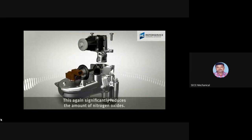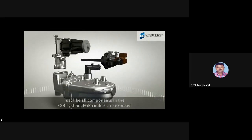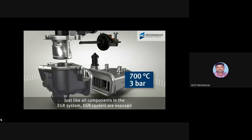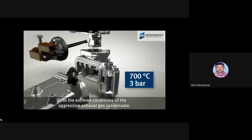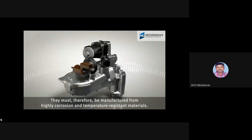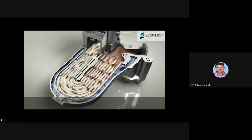This again significantly reduces the amount of nitrogen oxides. Just like all components in the EGR system, EGR coolers are exposed to the extreme conditions of the aggressive exhaust gas condensate. They must therefore be manufactured from highly corrosion and temperature resistant materials.